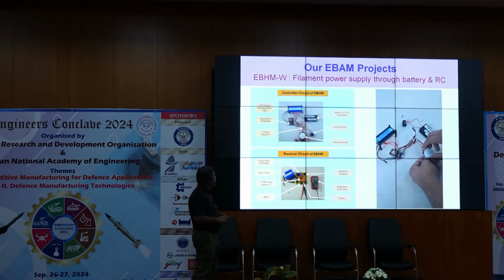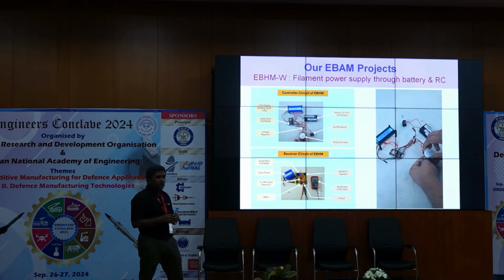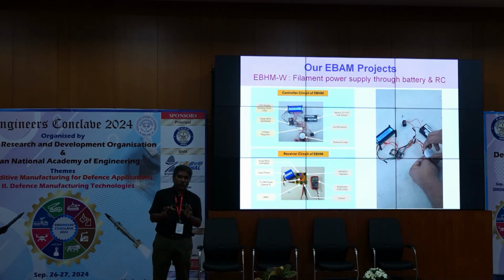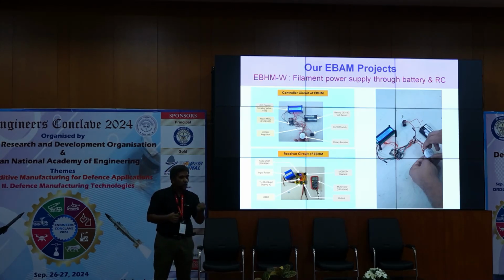Next please. Then we did another very interesting thing. I don't know how much you will be able to appreciate. I told you that there are 3 important power supplies. High voltage power supply, which is 60 kV, even 200 kV. At one end of it, the filament is connected to it. But the filament is actually a low voltage system. You need maximum 10 or 5 volt and current is about 50 ampere. But then you need to control the current. You cannot interfere because one end is at such a high potential, you will get a jolt.